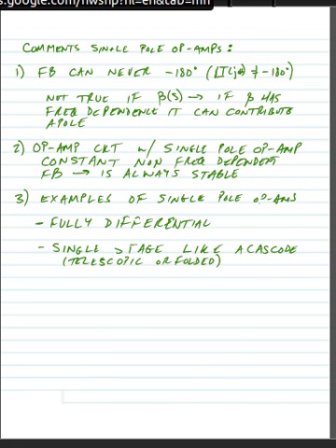So this is just like any other analog design trade-off. If we have an issue where stability is going to be quite a concern, or we have to operate our amplifier up to very high frequencies, we might have to suffer a trade-off between gain and stability. And so we might have to choose one of these topologies in order to make that happen.